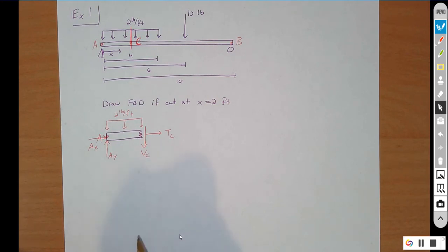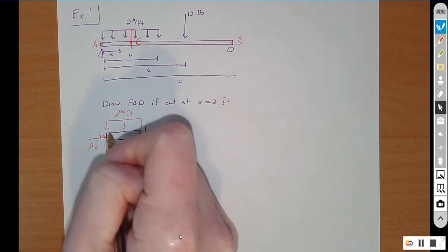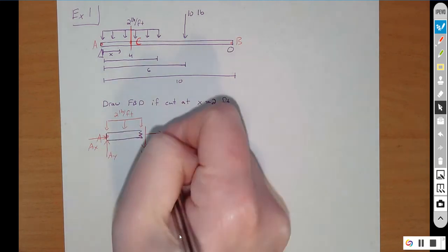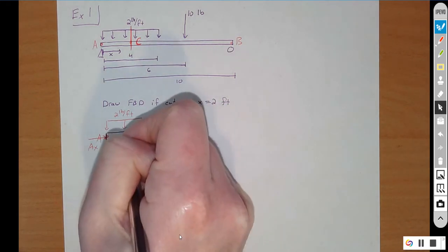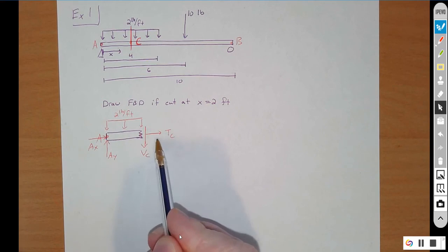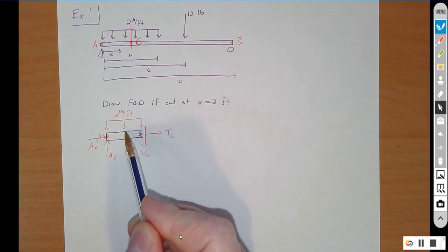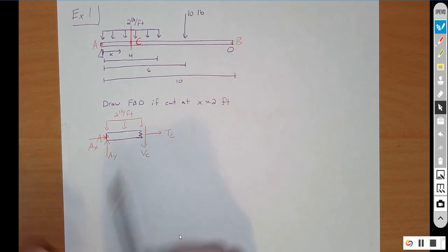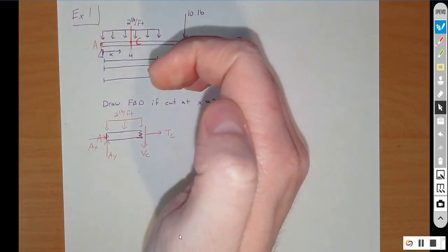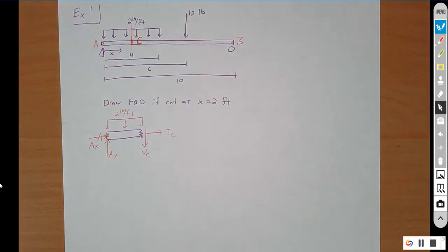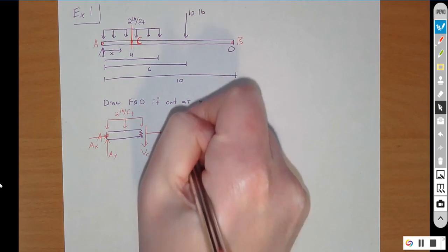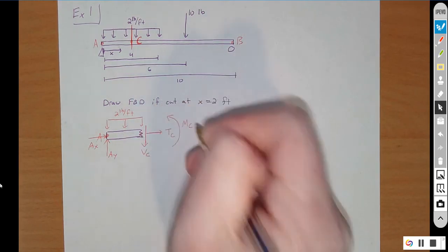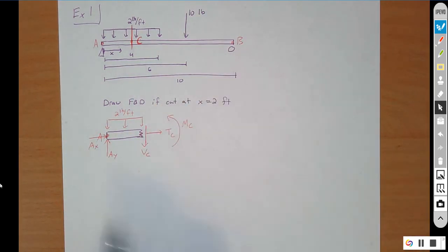And then the last piece here would be the moment. And again, we want to make a happy face. So in order to do that, we'd want to push down in the middle. So we'd want to have our moment come up and kind of. So again, imagine this side over here is fixed, and we're going to grab it with our hand, and we're going to like torque it. I'm sorry that the visualizer froze there. Maybe it'll come back. There we go. So we'll get a moment at C. So that's the left-hand side.